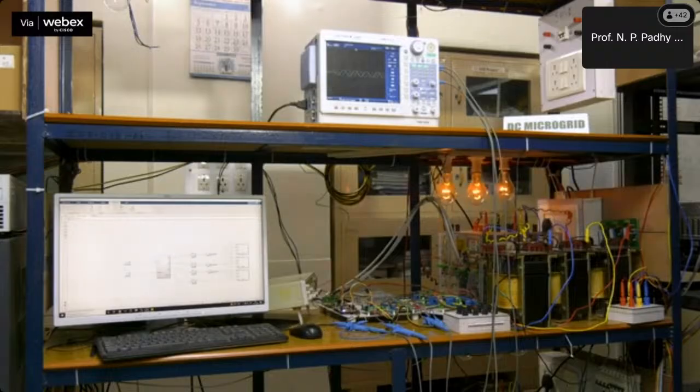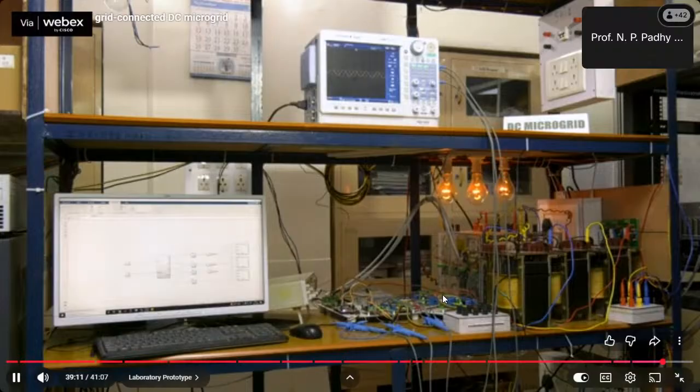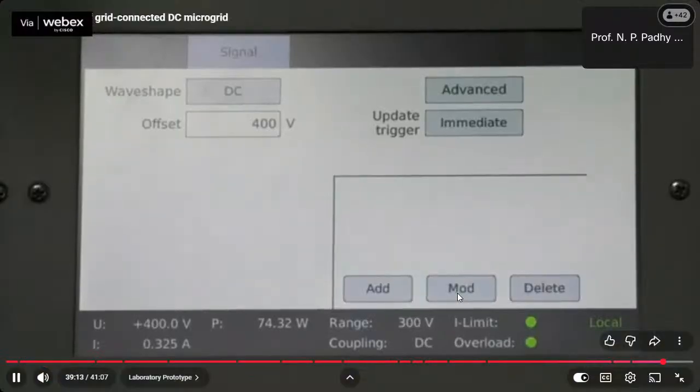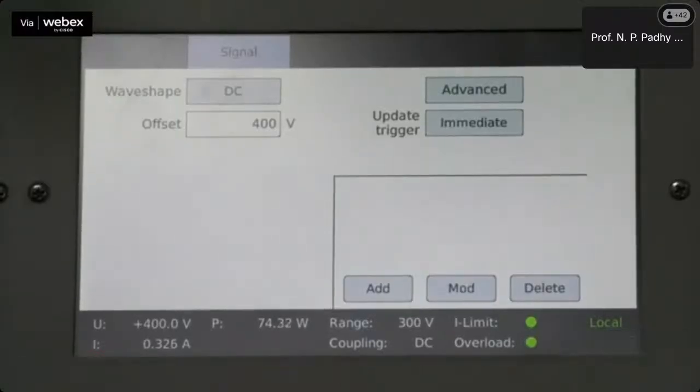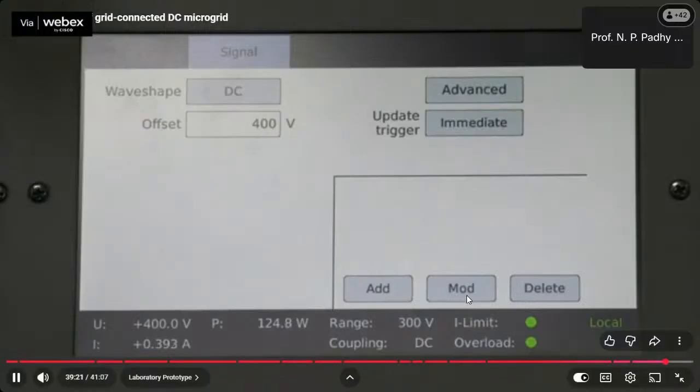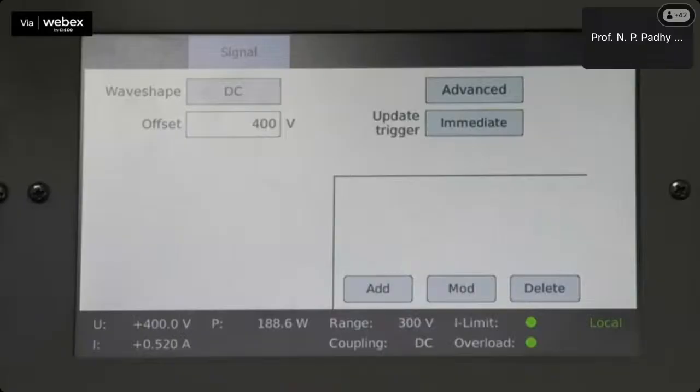After enabling the control system, by observing the DSO, there is a power flow between the DC bus and AC loads. The voltage and frequency at the AC load side are stable. By observing the DC microgrid emulator, that is, the power amplifier screen, the power sign is positive, which means it is giving power out, that is, the power is flowing from the DC bus to the AC load.